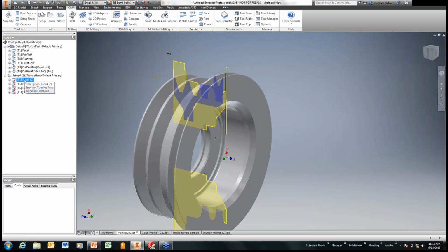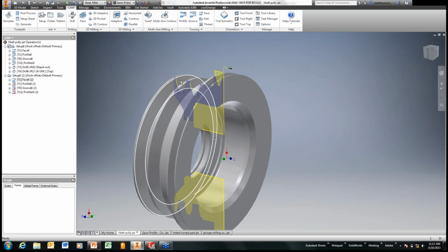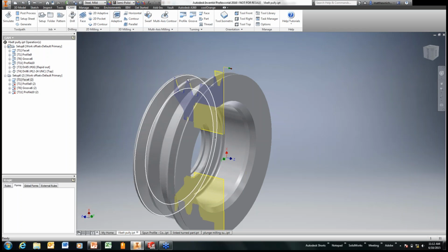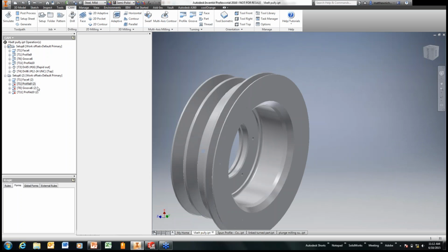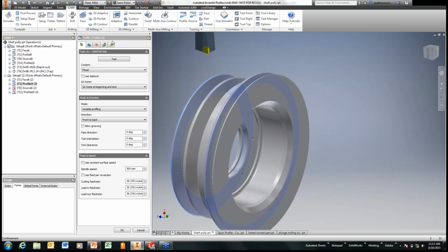So now once I do that, you can see here on the facing operation that my facing operation is now flipping to the back side. So all I need to do is hit generate. And now you can see that from checking continuous machining from previous setup, it's got all the stock removed still from the last setup. And now all I have to do is remove what I need to on this side. So it's just going to be going into these different setups or these different toolpaths and redefining confinements.